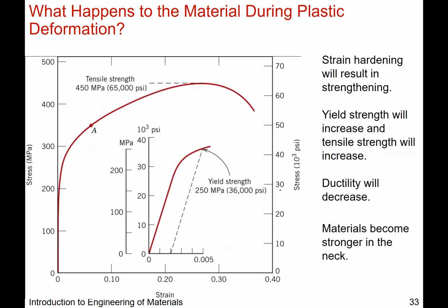Okay. I think I've actually said all of this, but this just drives home the point that what's happening at the neck, where that region gets smaller, the material is actually getting stronger, but you wouldn't know it if you plot it in this style where the stress strain curve is normalized by the original length, the L naught. If you were to actually instantaneously measure the cross-sectional area and the elongation at any given time, L sub i, so instantaneous, not L sub i as initial.